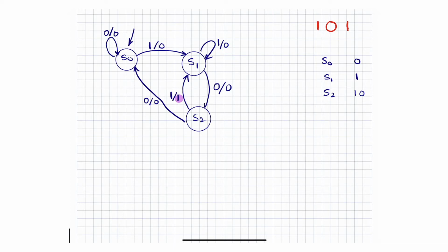And if you have multiple inputs, for example, here I only have an X, so each one of these states will have only 2 options to leave, either 0 or 1. But if you have, for example, 2, you will have 4 of these options, and you're going to have to account for all of them. And frankly speaking, this is the most important step in the design.